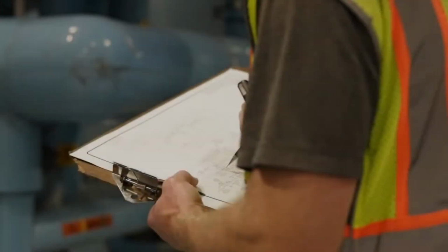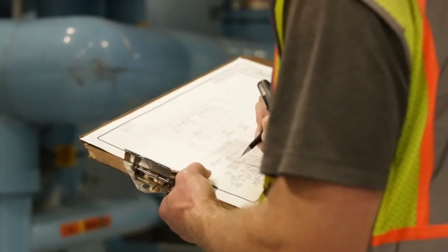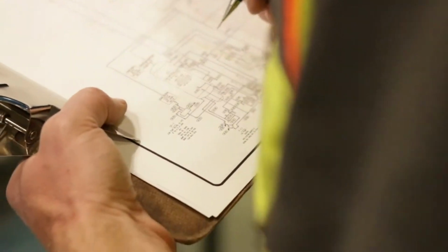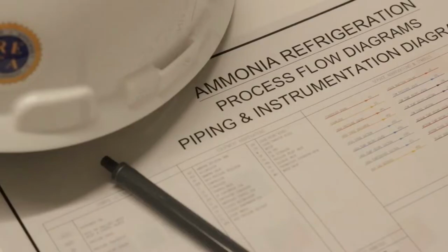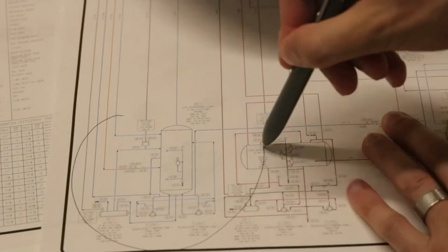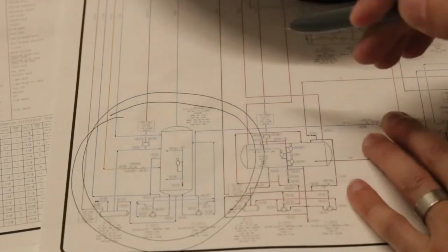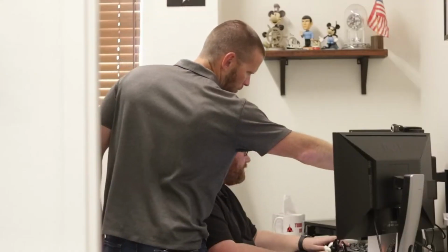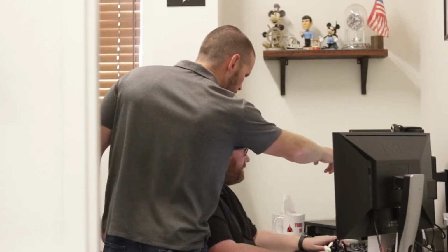If process safety information is the foundation of a PSM program, then P&IDs are the cornerstone. An engineer or technician who desires to familiarize themselves with a chemical process will often first turn to the P&IDs because of the detailed equipment information included on the diagrams. A P&ID is a diagram that depicts the interconnection of process equipment and instrumentation.